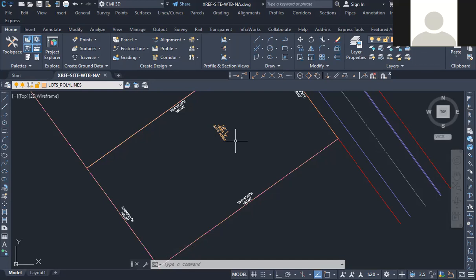Precision. Square foot, no decimal places. Normal rules for rounding. If it's 0.5, round up. If it's less than 0.5, round down. Okay. Acreage, only go to 3. Most of the time in surveying, we go to 4, but what you end up doing is you end up having to chase those 4 decimal places. What do I need? I know what the outbound of this whole lot is, right? So when I take all of your lots and I add them up, I should get that total, agree? If you take it out to 4 decimal places on the acreage, you're chasing that decimal point.